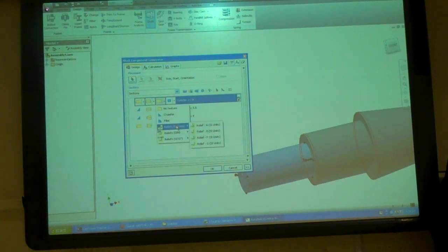So if we had a part like that, the part that's sitting, that slides on there, kind of wants to go that far. It can't go all the way, unless we added a chamfer in here, and then we could get it all the way, right? So if we wanted this to fit all the way flush, chamfer it so it can go in.